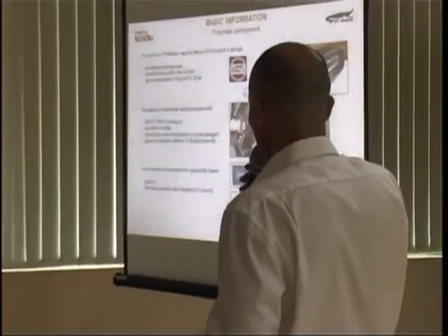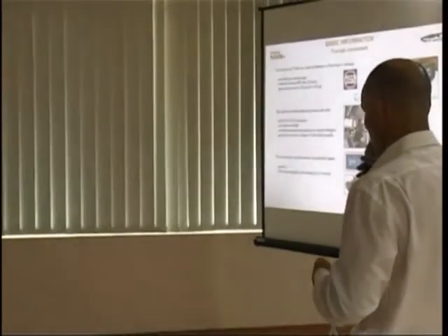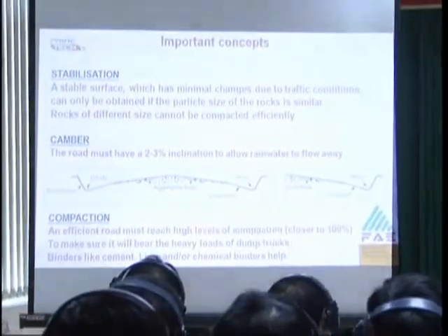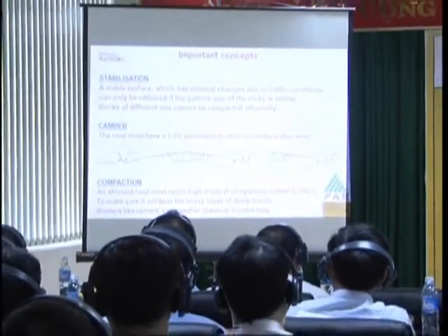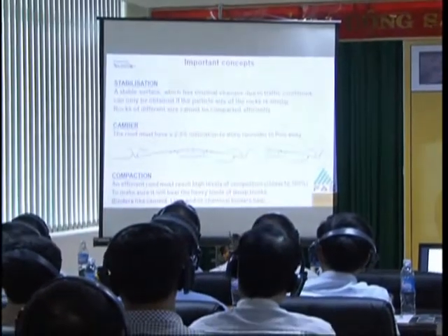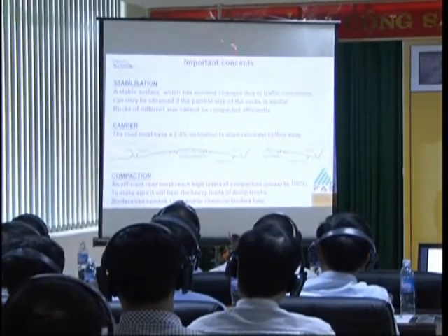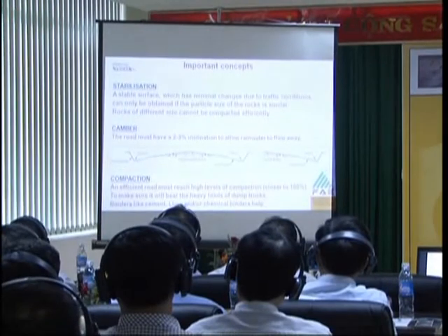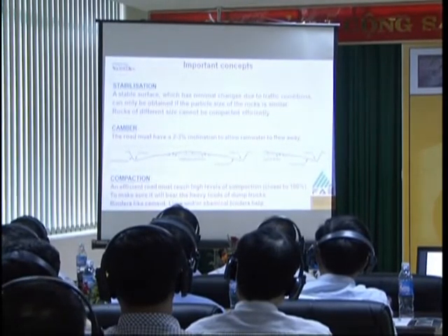And to make it stable, because when rain comes or when heavy traffic goes on the road, these move. So it's not stable. We want a road that is stable as much as possible. So, first concept, stabilization. We need to make it stable. Rocks must be similar size.